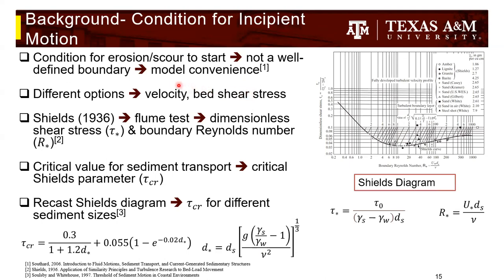First one is the velocity, essentially the velocity of the wave, which causes the particles or the surface to erode, and then the bed shear stresses. When the wave or the velocity of the wave comes on top of the surface, they impart some superficial shear stress. And once the shear stress overcomes the resistance from the soil, that causes the erosion. And that is one of the critical functions which essentially guides how the structure or the soil foundation around the system or in the levees will react to the surges or the wave impacts.